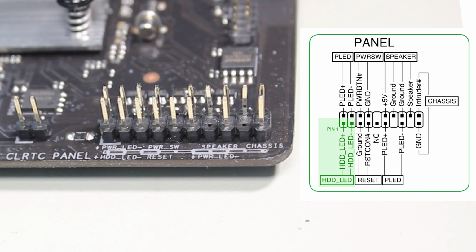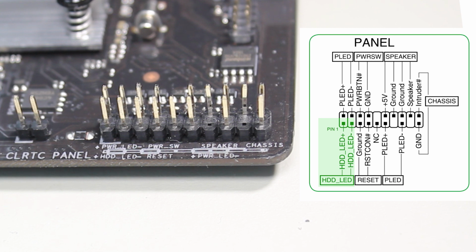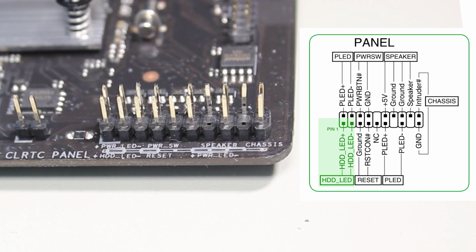I will start by plugging the LED light for hard disk activity. It is important, when you plug in a connector that is attached to an LED light, the positive and negative are connected correctly. If they are swapped around the wrong way, the LED light will not work. Computer cases generally indicate the positive and negative wires in two different ways. The first way is that a white wire is used for the negative wire and the positive wire will be a different color. The second way is that both wires will be black and positive and negative will be written or imprinted on the connector. In this case, the wires are both black and the connector has a positive and negative imprinted on it.